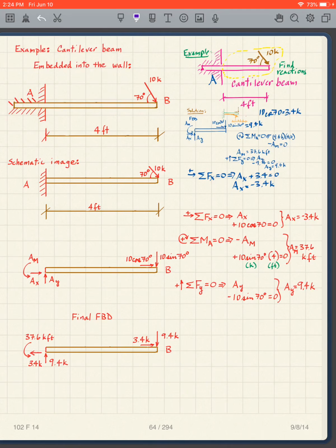Well, what do we find? This is not a roller. It is not a hinge. In other words, if I had a beam that was supported like this, and I have a hinge here, if I try to load it here, well, this does not resist bending. This is not stable. This thing is simply going to move in that direction. So I can't have that situation. It doesn't work.